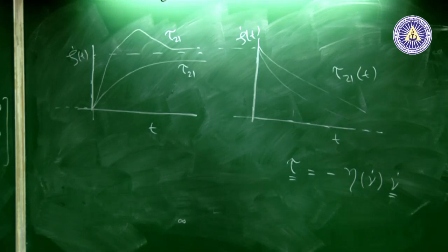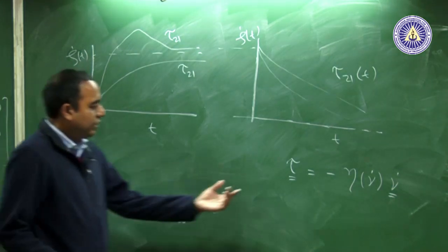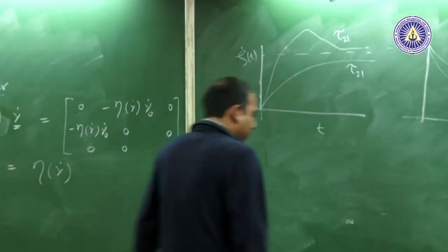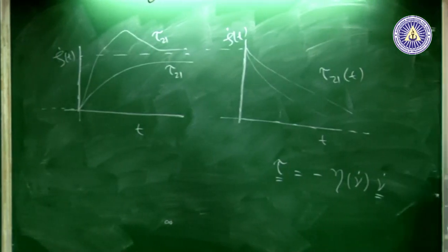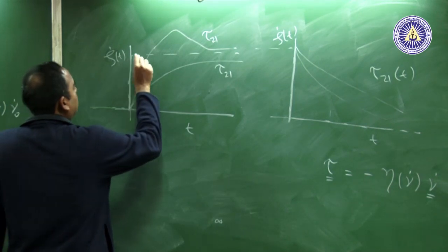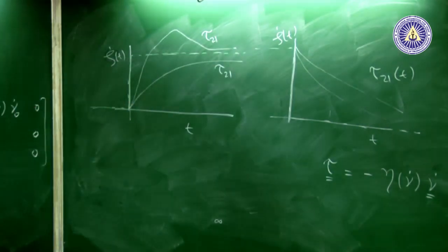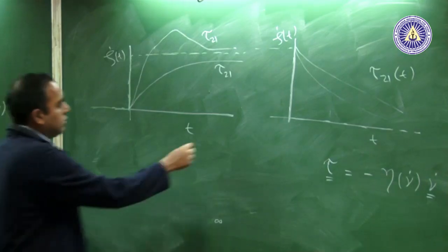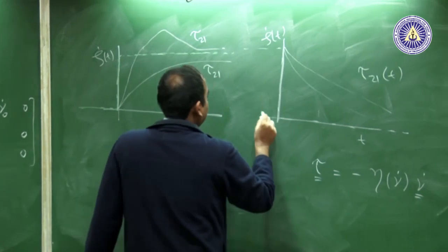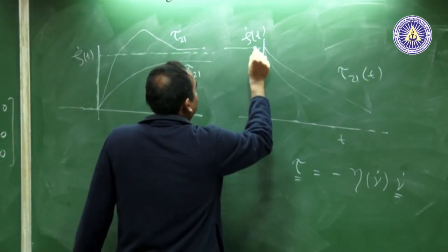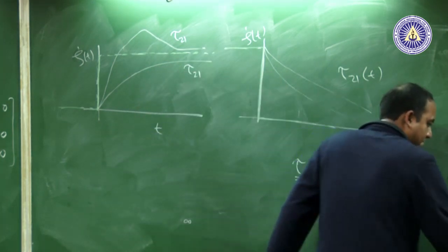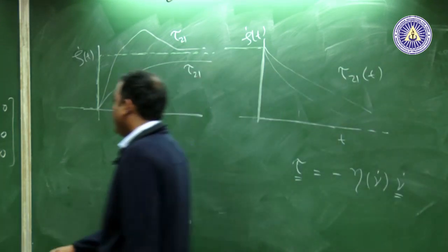However, for a generalized Newtonian fluid, because of its simplicity and because of it being a close family member of the Newtonian fluid, what you can only predict is what the Newtonian model predicts. So, for all classes of generalized Newtonian fluids, the shear stress would closely follow the strain rate that is imposed. If the strain rate is this way, the shear stress would follow it, and it would instantly show a decay. Now, this is the other limitation that we have.